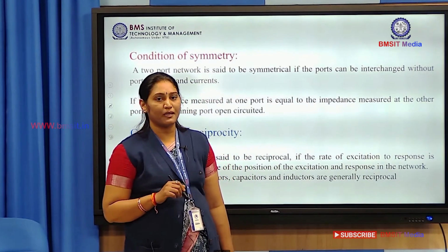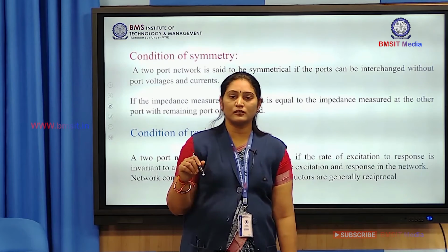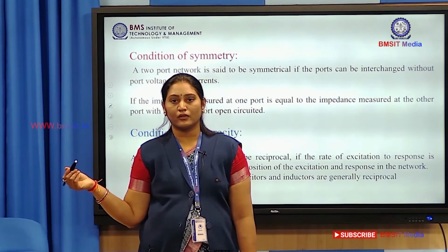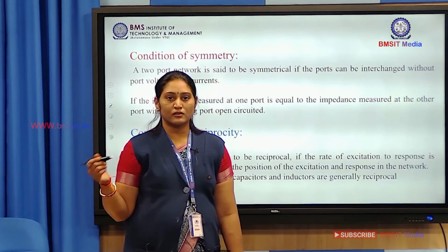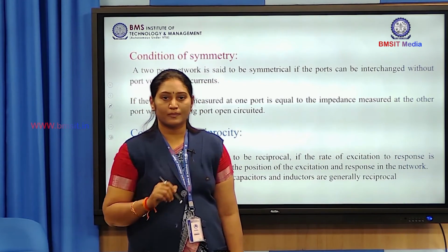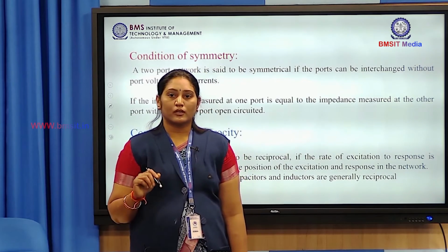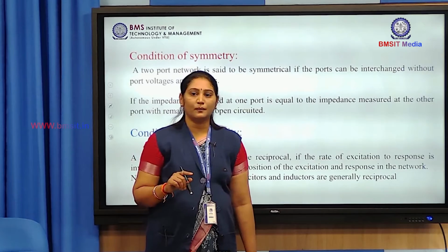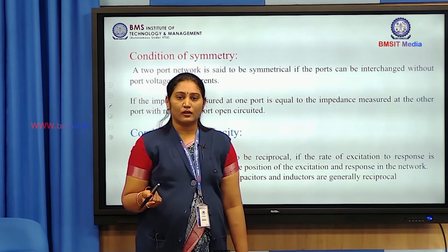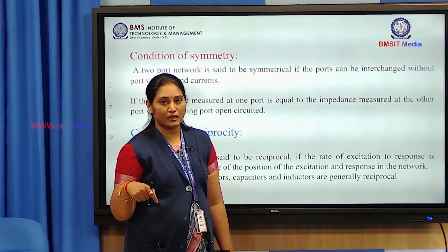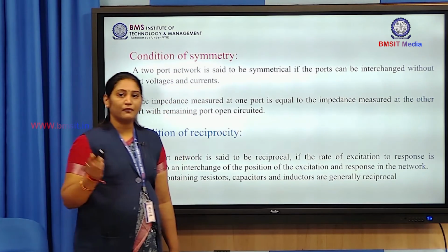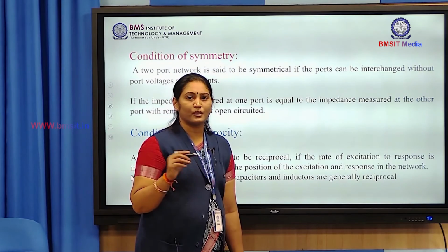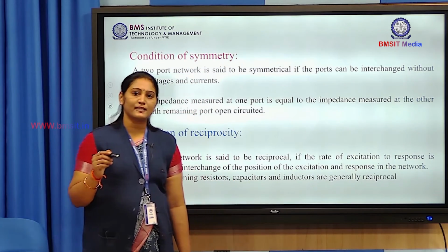In case of Z parameters, when I measure Z12, it is open circuited with port 2. When I measure Z21, it is open circuited with port 1. So if the impedance measured at one port is equal to the impedance measured at the other port, with the remaining port open circuit, then we can match the impedances from the input port and the output port, and we call that symmetrical.